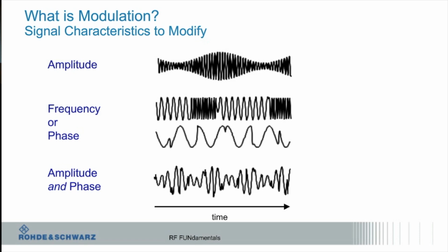But then in the end, you're going to do a combination of them, right? You're going to do typically amplitude and phase. So pretty much all digital modulation stuff that you see now is a combination of amplitude and phase modulation. So whether it's 802.11 or LTE or whatever, if you look at the underlying modulation, it's QAM. Okay?